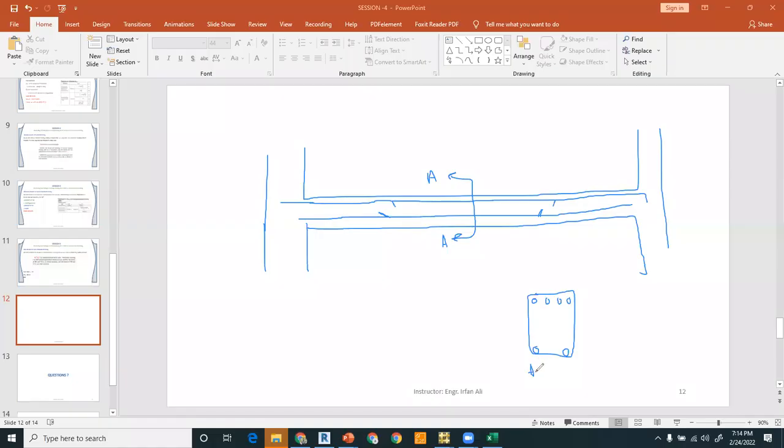And if I take a section over here, this is the support. Let us call it section BB. So if I draw the section over here, at this support, we said that there will be 8 bars at the top. And there will be 2 bars at the bottom of the support, because there will be 4 bars at the mid. So here it is 4. So this is 4 bars.